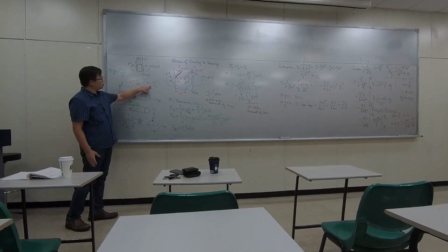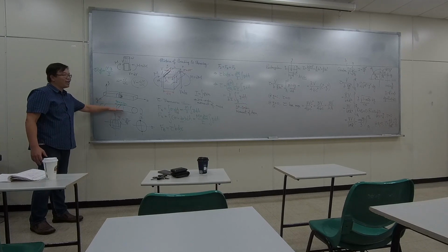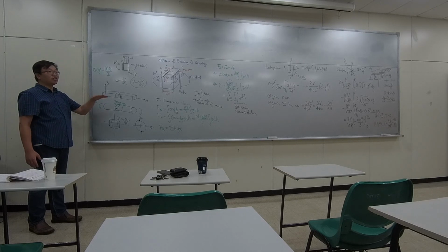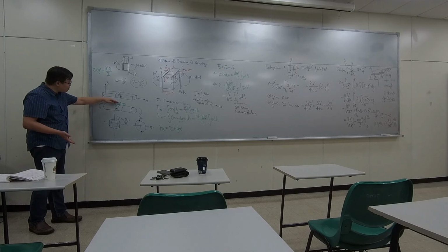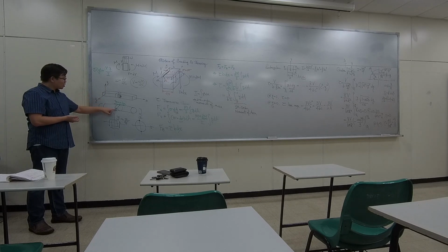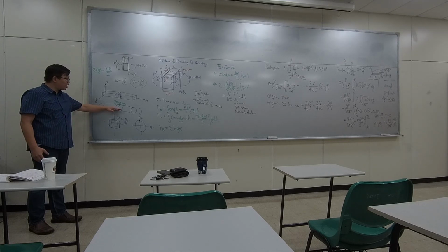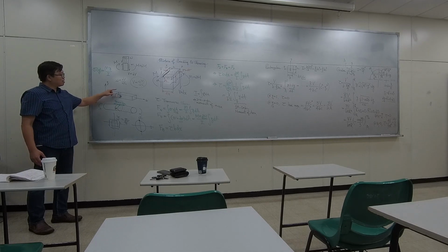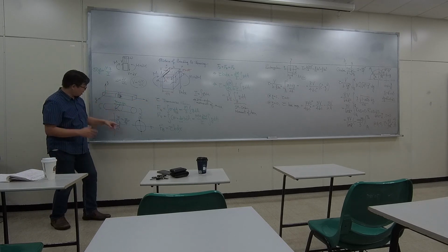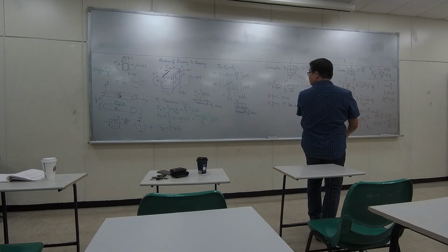When there is a change of moment, at the neutral plane, actually everywhere inside this cross section, there's horizontal transverse shear. It's everywhere. However, at the very top, that shear is 0. So when we are talking about the point on the side, actually that's on the neutral plane, and that's where we have the largest transverse shear. And the magnitude can be computed by that exact equation, 4V over 3A.